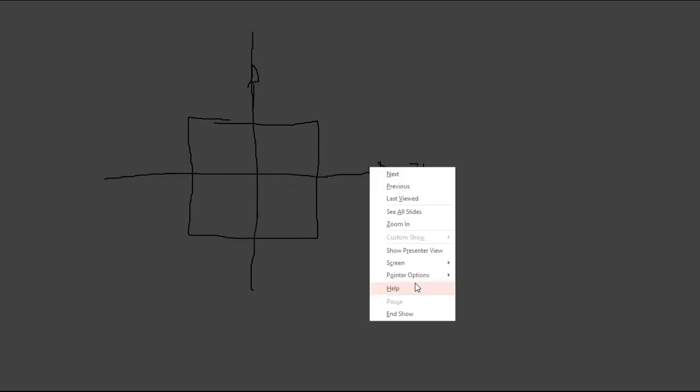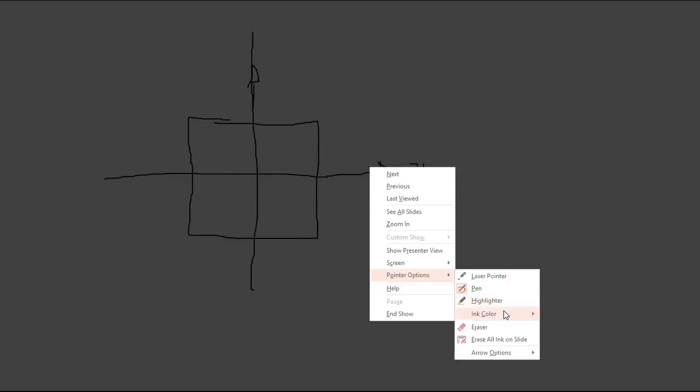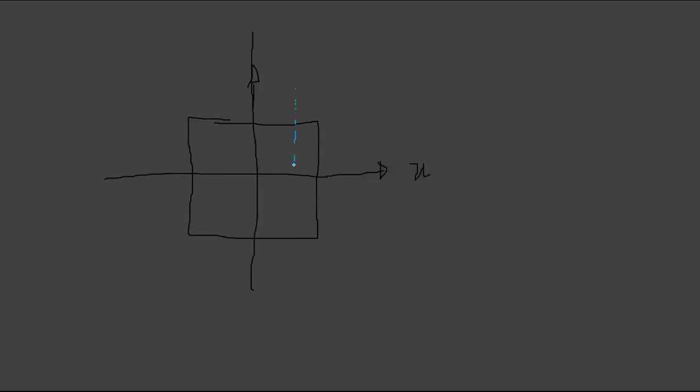So let's plot an original element. So this is your original element, right? So what happens is, in x direction, you have a negative strain, right? So that means your element has contracted in x direction. It's like this. So definitely, then it should elongate in y direction, right?